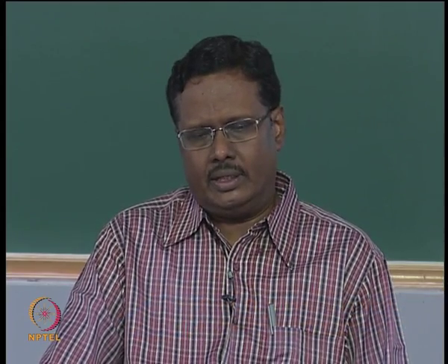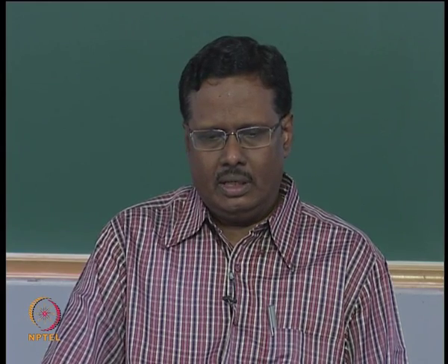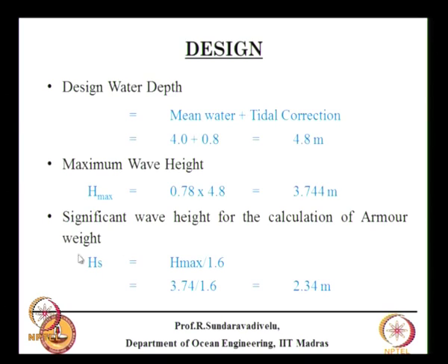Last class we have seen the design of breakwater. We will continue the design. We were designing for 4 meter water depth with surge and other high tide levels giving 4.8 meter. Maximum wave height we have calculated 0.78 times the water depth, and we have to design for significant wave height, not for the maximum wave height.